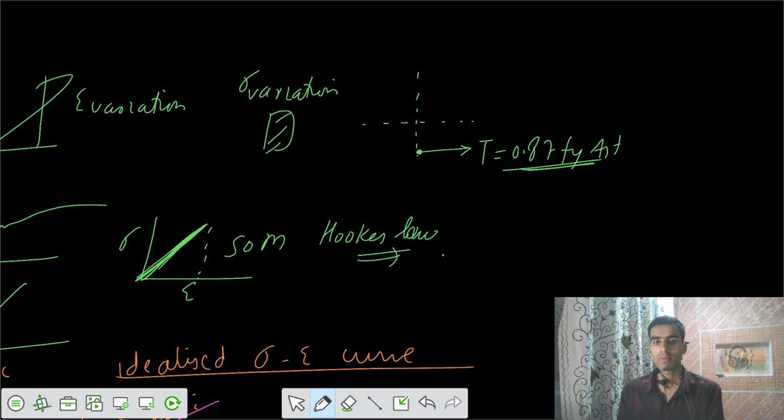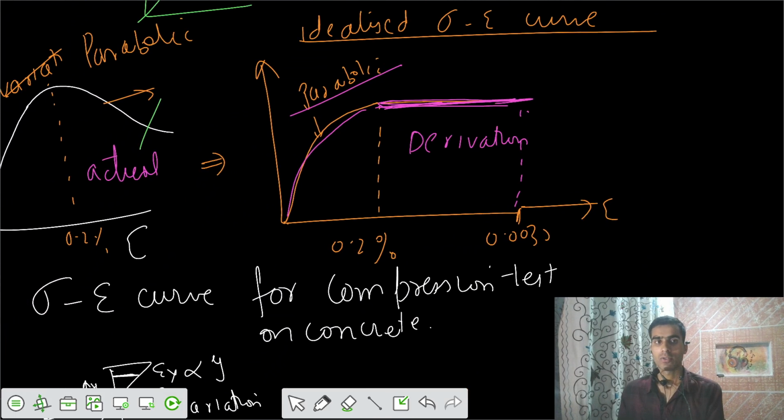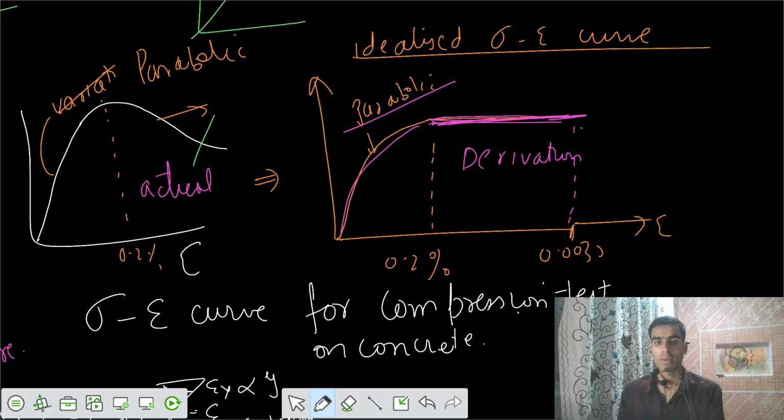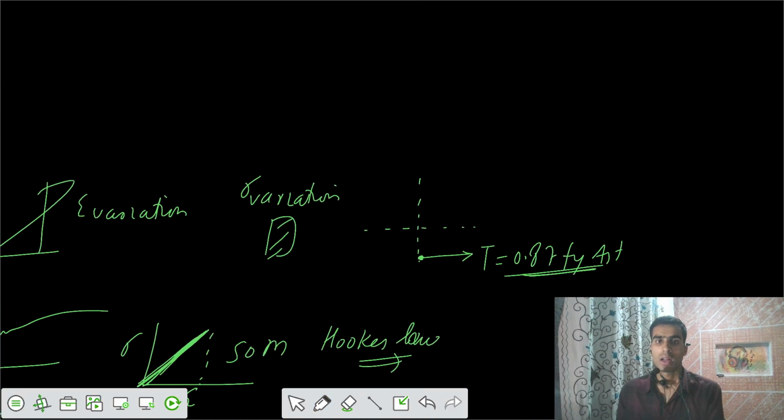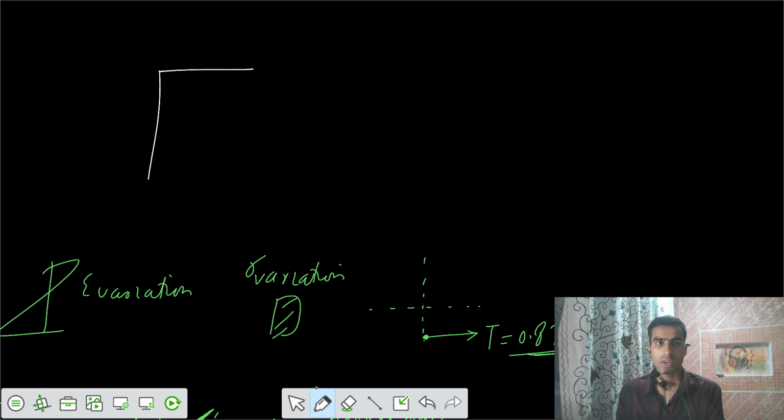And from the top side, we have to see what our diagram for the concrete should be. From the top side, we say your stress-strain diagram is in this fashion. So we have to make the same sort of stress block for your concrete. That's your compression zone. The same sort of curve has to be used for this case, corresponding to the maximum strain in the top extreme fiber, that was your 0.0035. This is assumption 2: strain in the top compression fiber is equal to 0.0035.